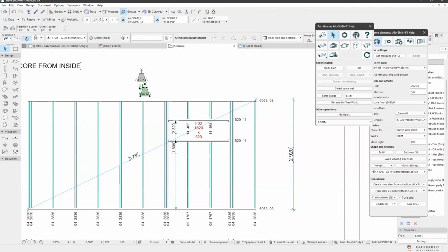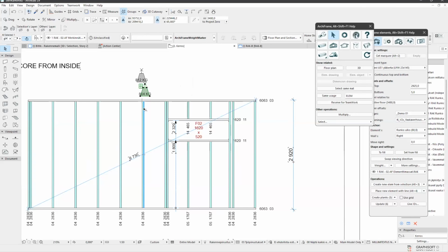So in this case, they are lifting these inside the factory, so then they are interested in this weight, and then at the building site when the windows are installed, this is the final weight. And they're also interested in the balance point, so where to put the mounting lifting place. So there is the center of gravity to define the lifting points.